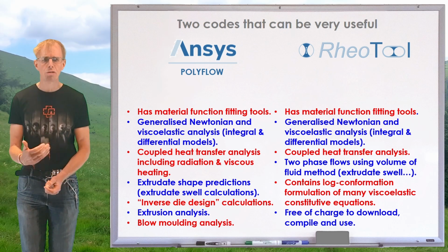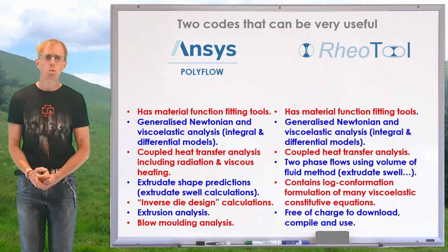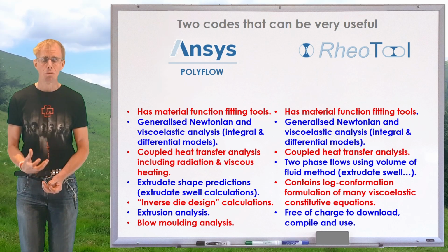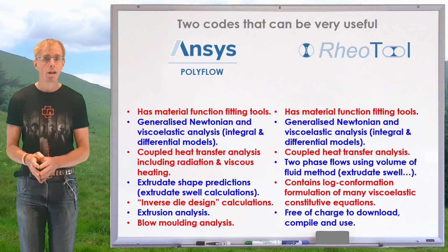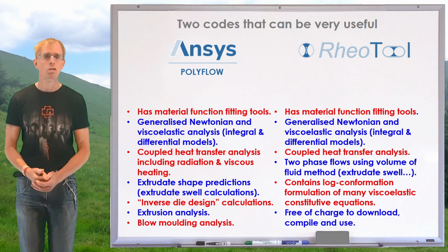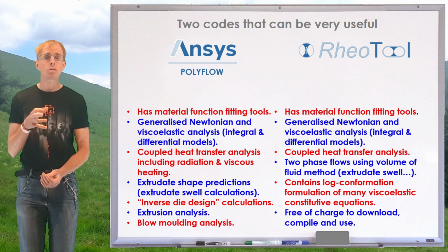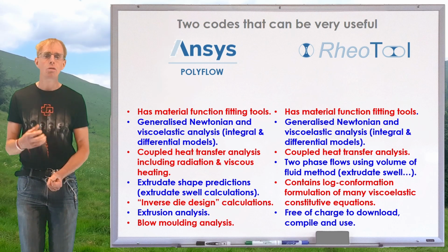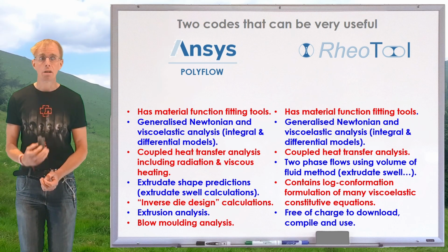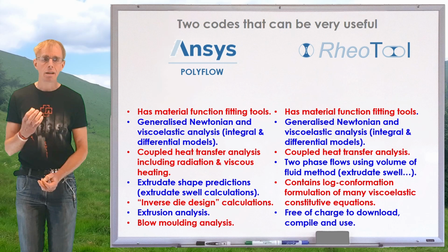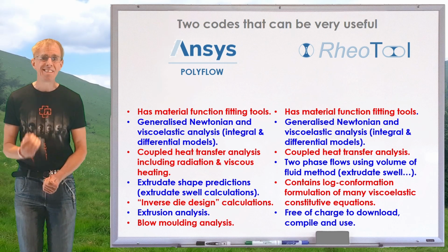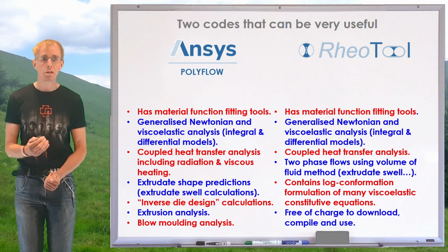And again, in terms of scale, I used to use RheoTool on a cluster with several hundred CPUs, because that was the scale of problem that I needed. And solution times, and it was fairly old equipment by modern standards, but solution times used to be order of weeks. So these are not quick calculations to run. And so ahead of time, before committing to a flow modeling code, you need to also think fairly carefully about what compute you can afford and about what problems realistically you can solve with the compute that you can afford.